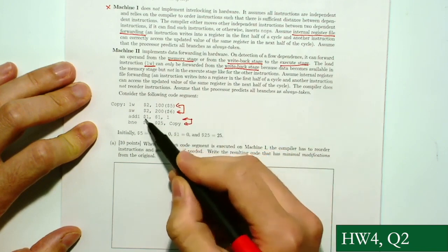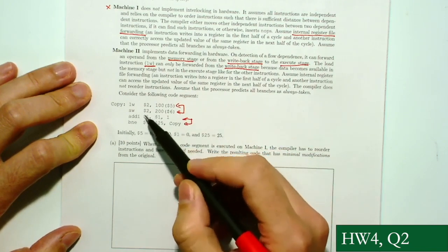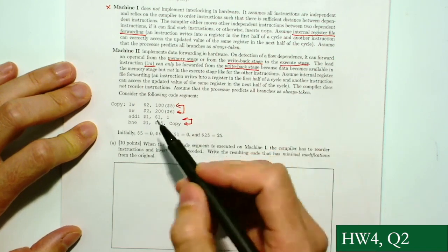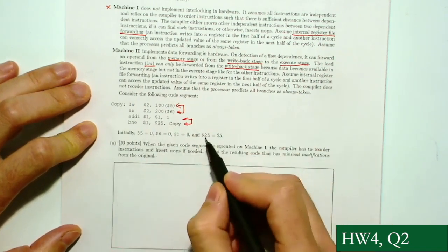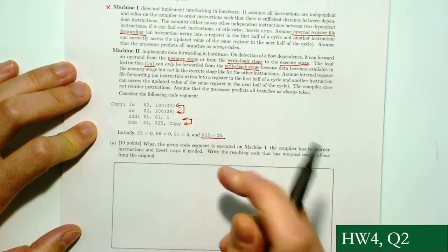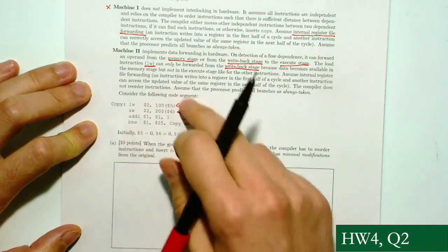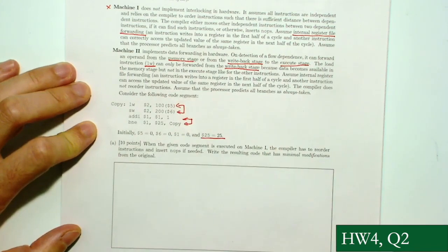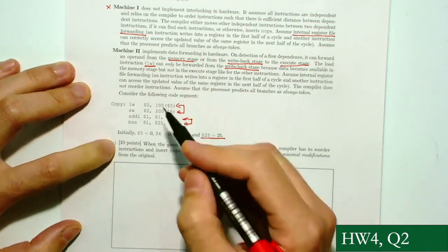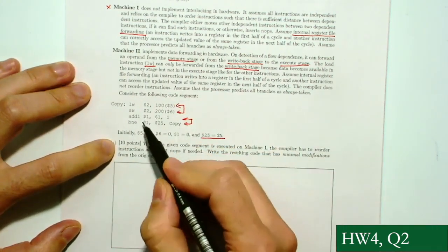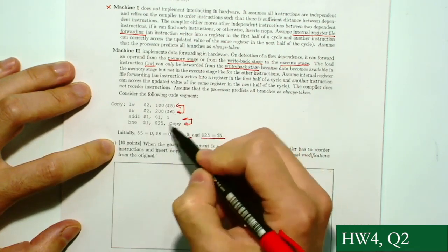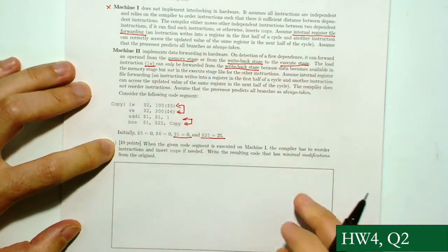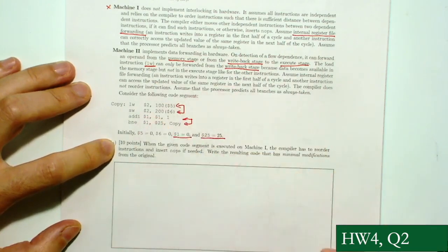So we add in this, we store the result of the add in this register 1, and we compare register 1 with register 25. So we have register 25 here, the content is 25, so we execute this loop basically 25 times. Because the initial value of register 1 is 0, so we increment each time, in each loop we increment this register.